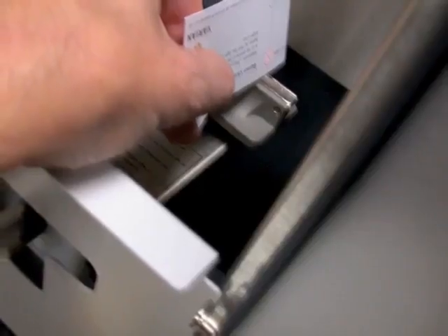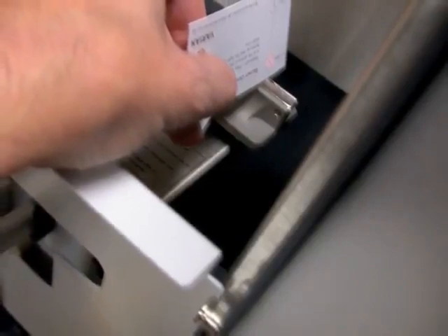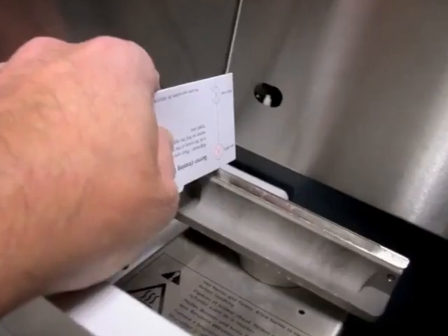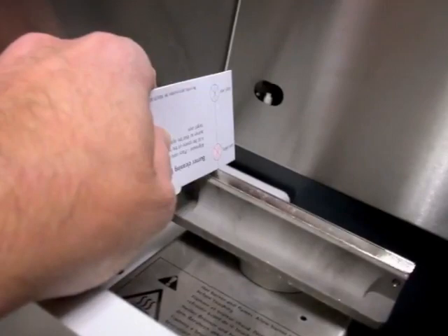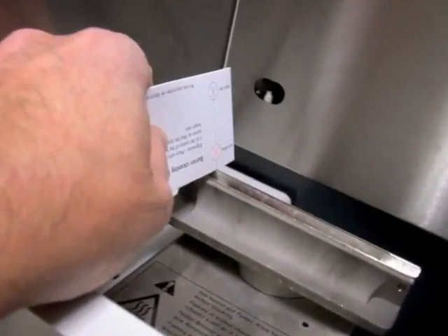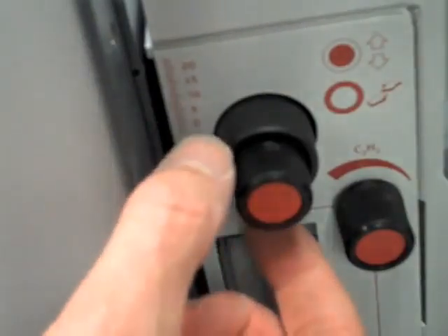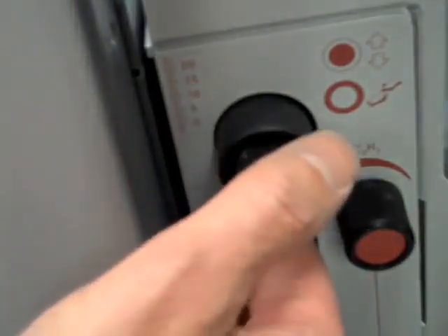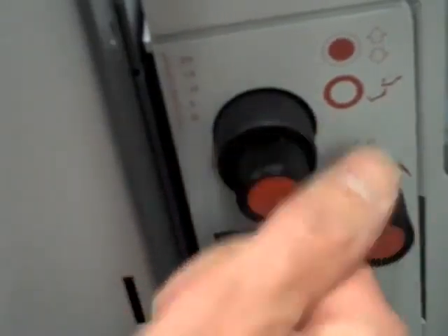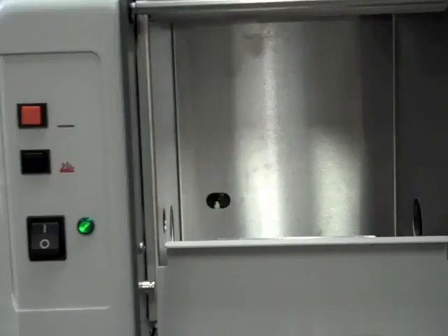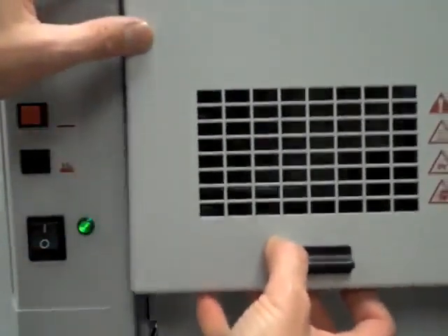If the beam is aligned in the target on the right-hand side of the slot and on the left-hand side of the slot, everything is in position as it should be. You can control the position of the burner up and down or forward and back with this pair of knobs on the left-hand side of the front panel. Replace the safety shield on the front before proceeding.